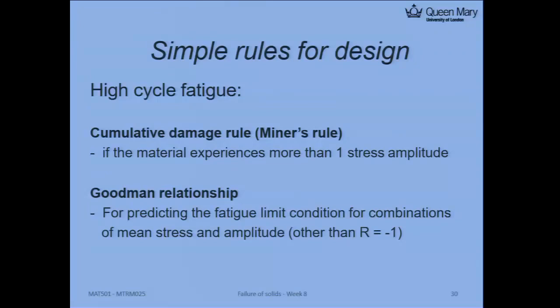Okay? So there are some simple rules for design. There are two rules here which are both useful. They look at this problem from different angles. The first one is called the cumulative damage rule. There's another name for it, Miner's rule. This is the name of one mechanician. So that means if the material experiences more than one stress amplitude,